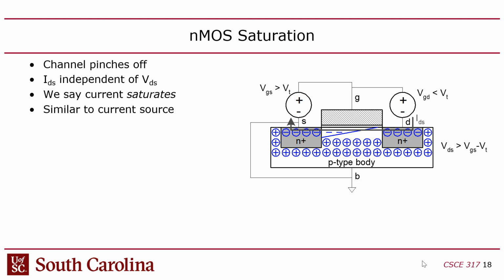So small, it might go under the threshold voltage, right? But the difference between the gate and the source voltage, that's no problem. But what ends up happening is you get a channel that gets squeezed, because over on this side of the channel you have a bunch of charge carriers, because the electric field on this one is going to bring up these electrons. But there's no electric field on this side because the difference between the gate and drain is not enough. You might say, why isn't it enough?